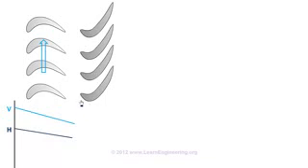Stators are also a set of blades, but these blades are stationary. They won't take part in energy transfer. What they do is simply transform energy from one form to another, or more precisely, they transform the enthalpy energy into kinetic energy. You can see the cross-section area of the nozzle decreases with flow, so due to its special shape the velocity increases. But at the same time enthalpy decreases. If you sum the change in enthalpy and kinetic energy, there won't be any change.